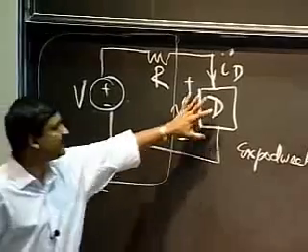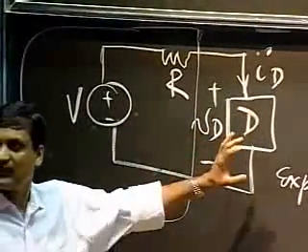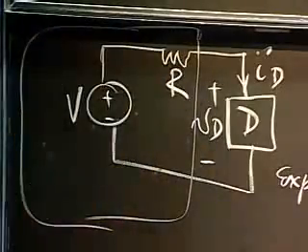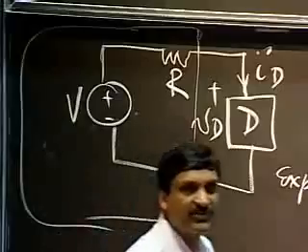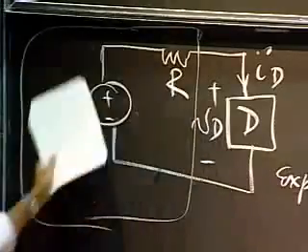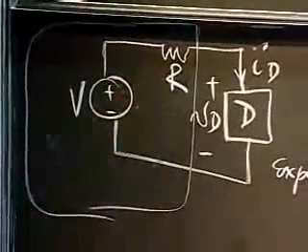If all you care about is the behavior of the nonlinear device, for the purpose of analyzing this nonlinear device, you can take this entire linear circuit. No matter how complicated it is, voltage sources, current sources, resistors, and a bunch of other funky stuff, you can boil all of that down to a Thevenin equivalent, a voltage and a resistor in series.